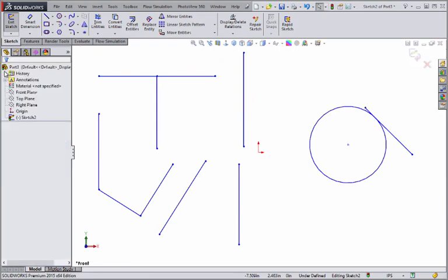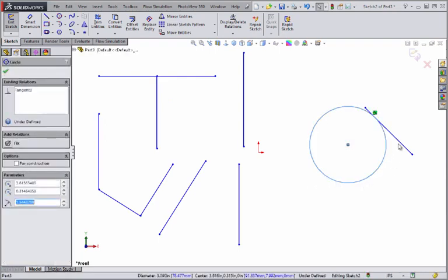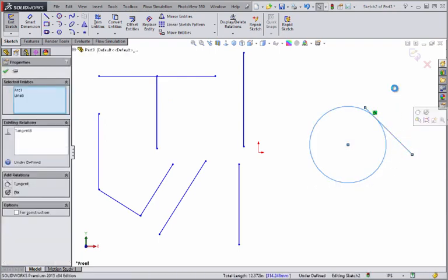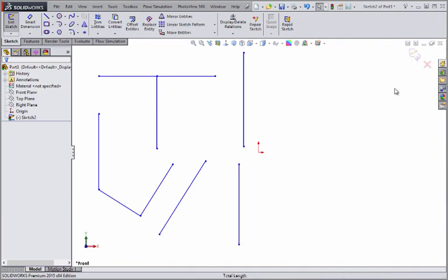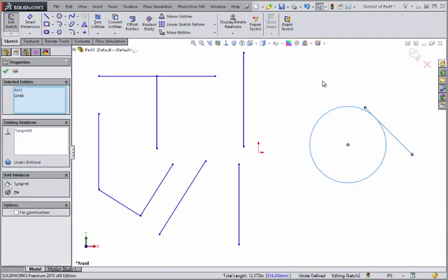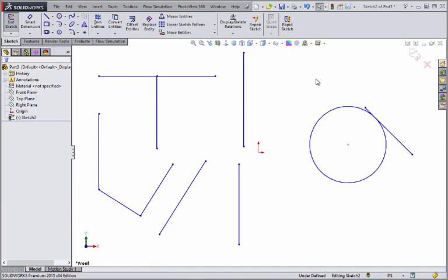Lastly, I'd like to delete some of the sketch entities I've created up to this point, so I'll use this opportunity to show you a few selection methods. Now I could Control select the geometry I want to remove, and then press the Delete key, but this can be problematic, especially if there are several items that need to be selected. The preferred method for selecting multiple items is the Window Selection method.